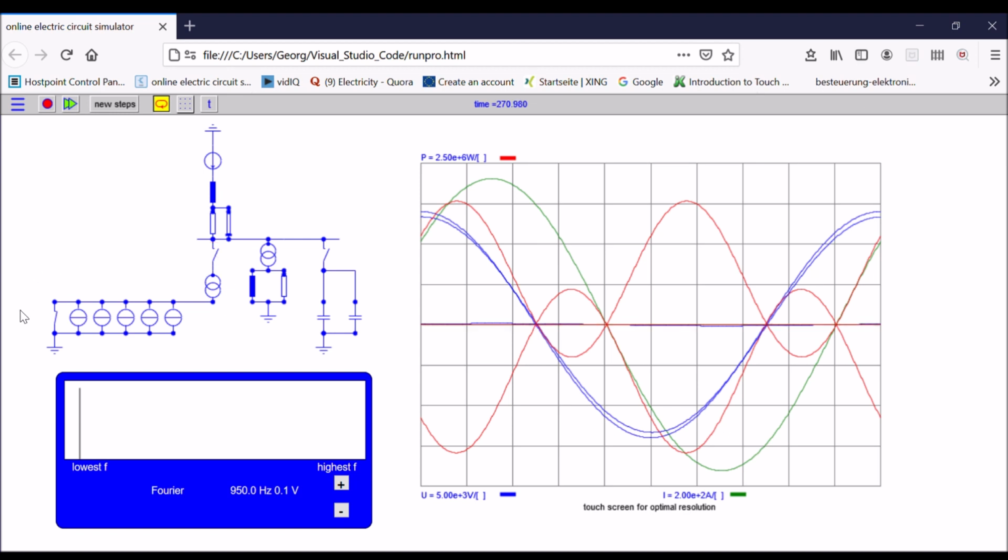It is a converter. Instead of a series connection of voltage sources with different harmonic frequencies, I have chosen to go for a parallel connection of current sources, but the effect is exactly the same. For the time being, I leave the converter disconnected and short circuit, so there is at the moment no harmonics spread out in the distribution grid.